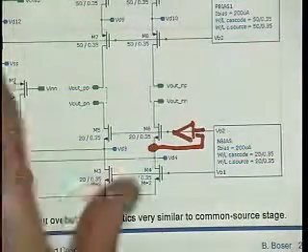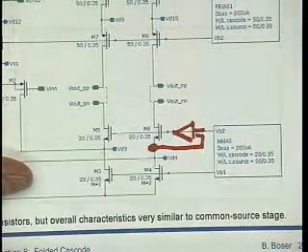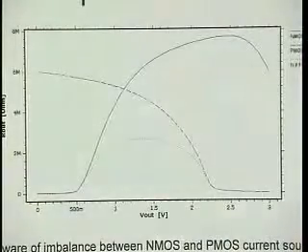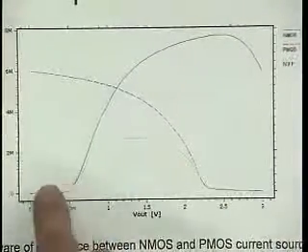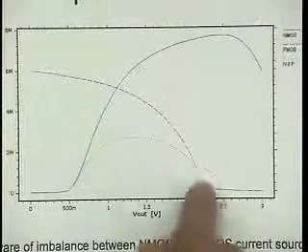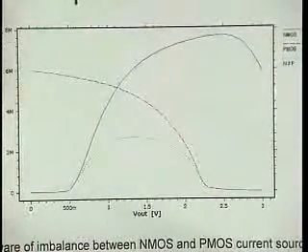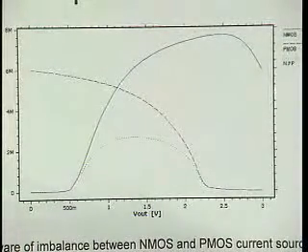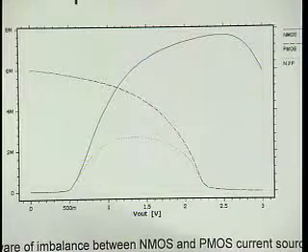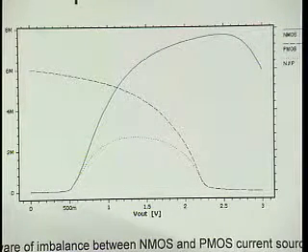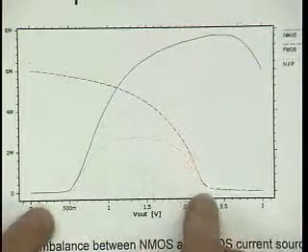The output voltage now becomes the bias point in my measurement, and then I get a picture that looks something like this, where this is the total output impedance. It's going to look totally symmetrical. I can't say whether the PMOS has infinite output impedance and the NMOS is at fault so that we don't get infinite gain. I can't see this from the combination.